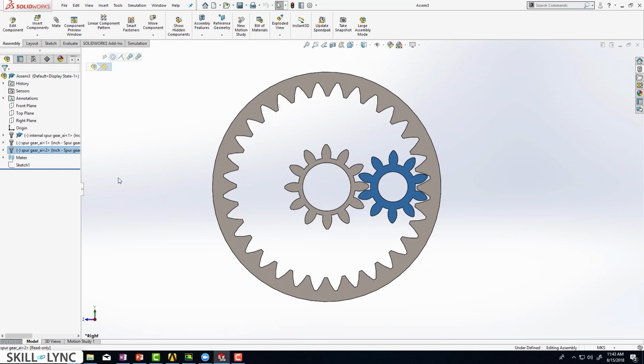That's basically it. Similarly, you have something called the diameter pitch. The diameter pitch is nothing but the inverse of module. If you're using the metric system, then typically we use a module specification. If it's inch based, then you go for diameter pitch. Now, in order for the 2 gears to mate correctly and transfer power correctly, the pitch circles of both the gears should be tangent to each other. And in addition to this, the module should be the same for the 2 gears.